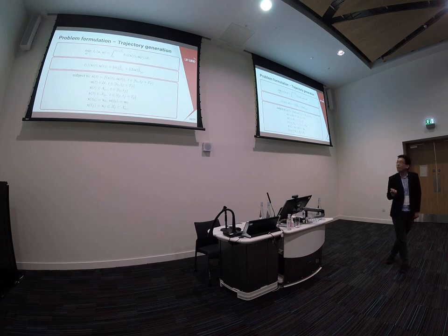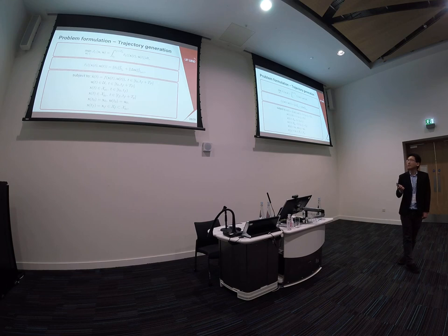So how do we formulate the trajectory generation? We minimize the cost function, which is composed of the thrust and the input deviation. We see that both deep stall and perch can be executed without thrust. And for the input deviation, we don't want any abrupt behavior.